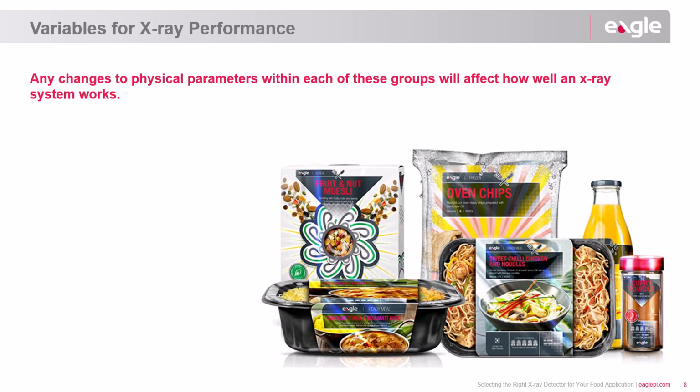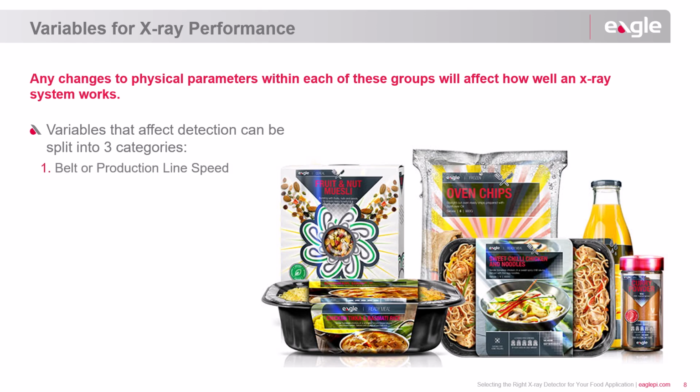When it comes to X-ray detection performance, there are 3 key factors to consider when choosing the right setup. Speed refers to how fast your product moves along the production line. The faster the speed, the less time the X-ray system has to analyze each item. If products move too quickly, the X-ray may not capture a clear image, which increases the chance of missing contaminants. Higher speeds might also require stronger X-ray power, or could introduce more noise into the images.